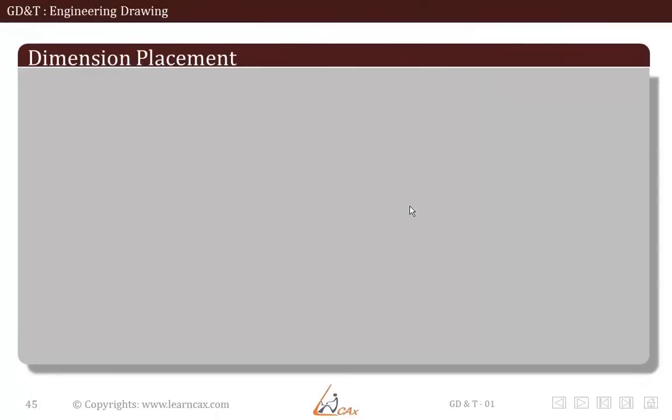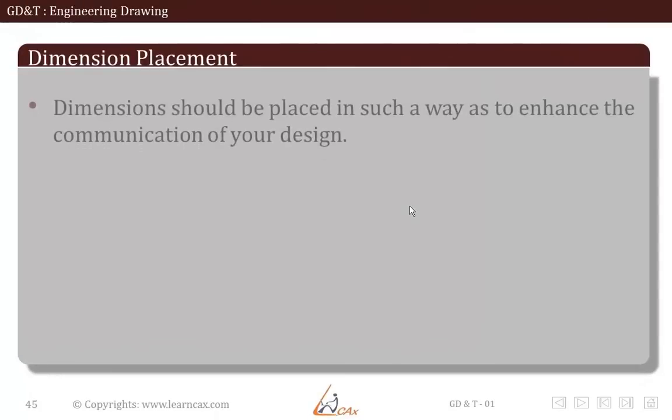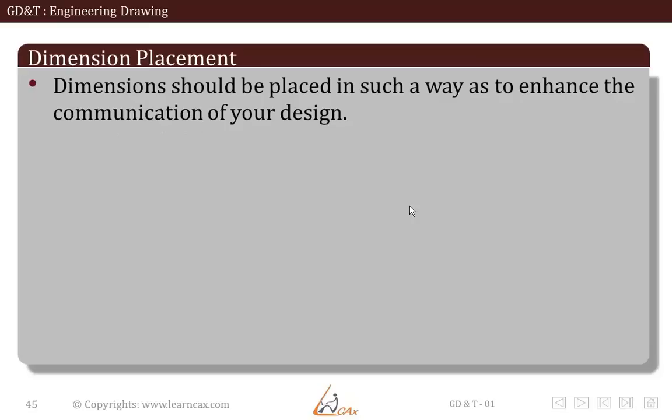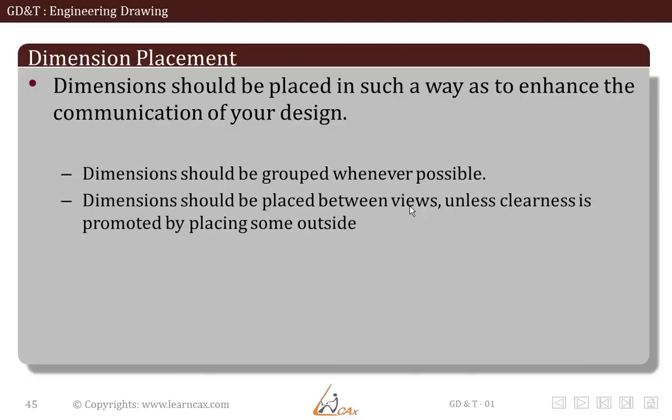Now let us talk about dimension placement. They should be placed in such a way as to enhance the communication of your design, not to confuse. They should be grouped whenever possible. Dimensions should be placed more often between the views unless it becomes congested.